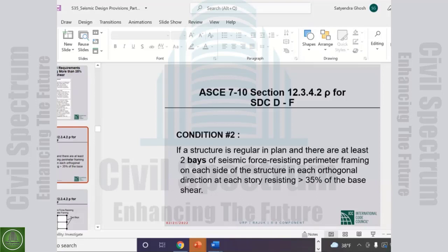So you have to design for the shear, you have to design for the bending, and the basics still apply. If you have high compression, you will have to confine. Other than that, there is no particular detailing requirement.